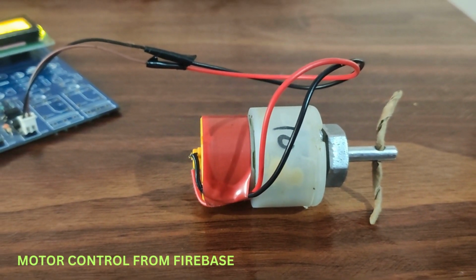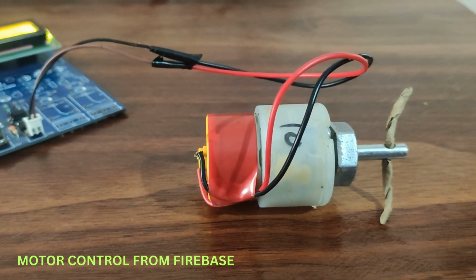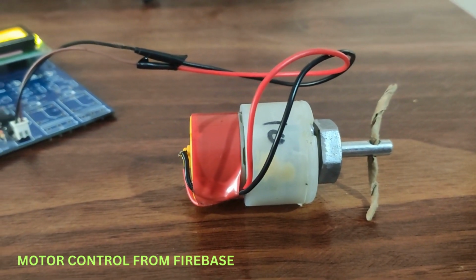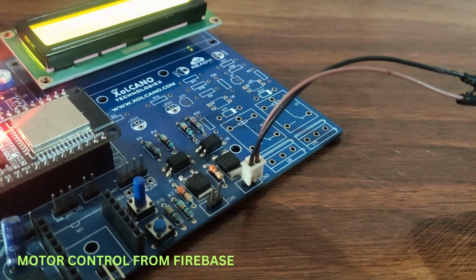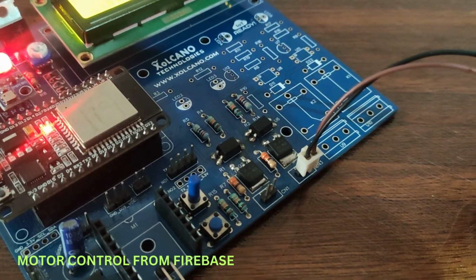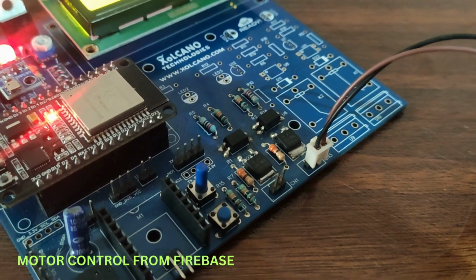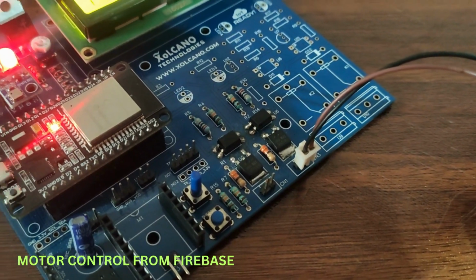In this project, I will be controlling a DC motor using the ESP32 development kit. This is the 10 RPM geared DC motor which works at 12 volts. It is connected to a MOSFET based driver circuit. There are two MOSFET based motor drivers on this board, which are connected to GPIO 2 and 4. Our motor is connected to one of these drivers.